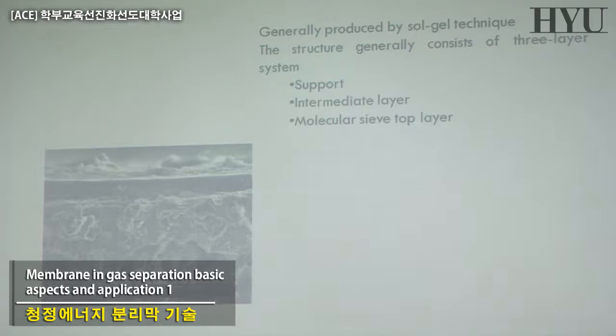Inorganic membranes can normally be produced using traditional systems. The sol-gel technique is the most utilized, for example, in preparing zeolite membranes. Zeolite membranes are one of the areas in which there is a lot of research today, because people are learning how to make a relatively homogeneous distribution of crystals of zeolites on some support.